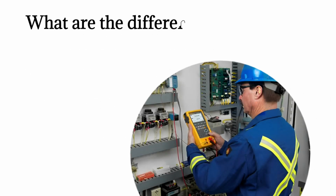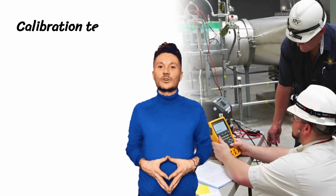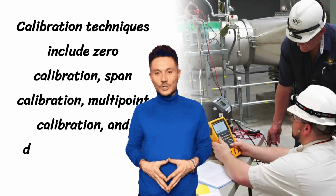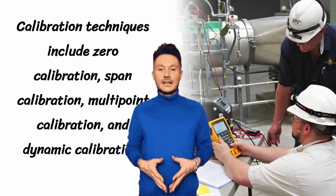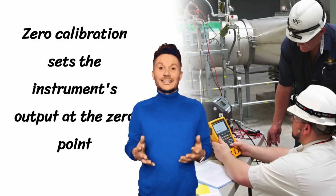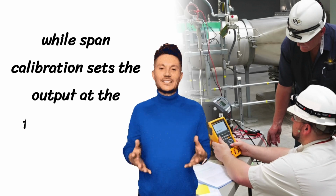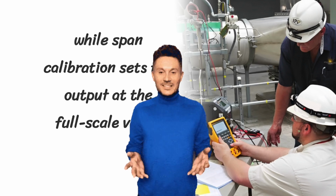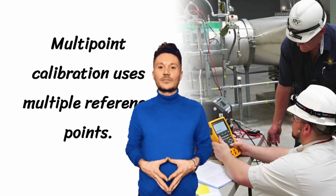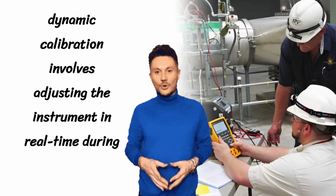Next question is, what are the different calibration techniques? Calibration techniques include zero calibration, span calibration, multi-point calibration, and dynamic calibration. Zero calibration sets the instrument's output at the 0 point, while span calibration sets the output at the full-scale value. Multi-point calibration uses multiple reference points. Dynamic calibration involves adjusting the instrument in real time during operation.